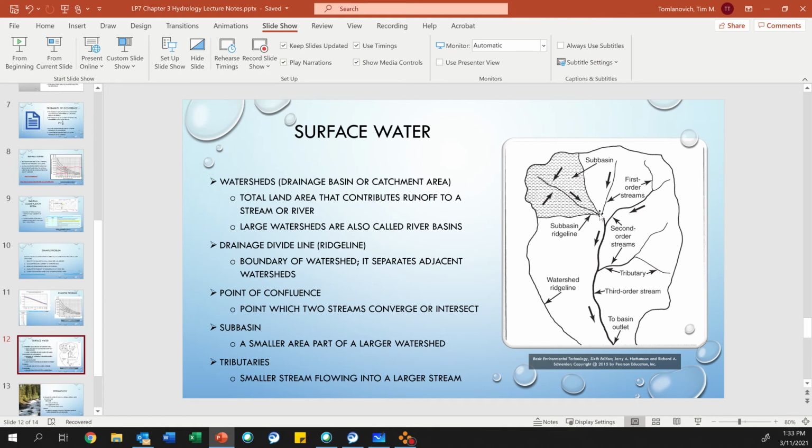Once you figure out that volume of flow going to that river, then you can calculate the flow going down the stream until where you need to figure out the total flow, because we have the sheet flow and then all of this coming down. So at the end, just like sanitary sewer design, the flow gets bigger and bigger as it gets down to the outlet. Okay.